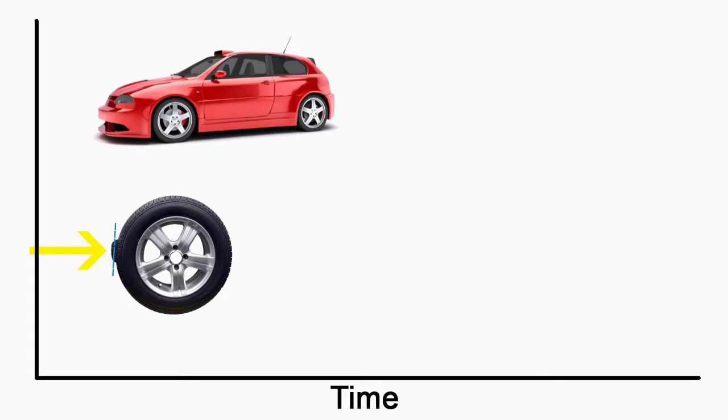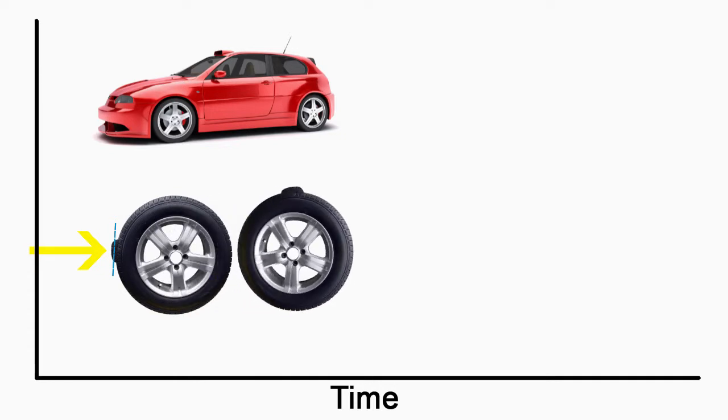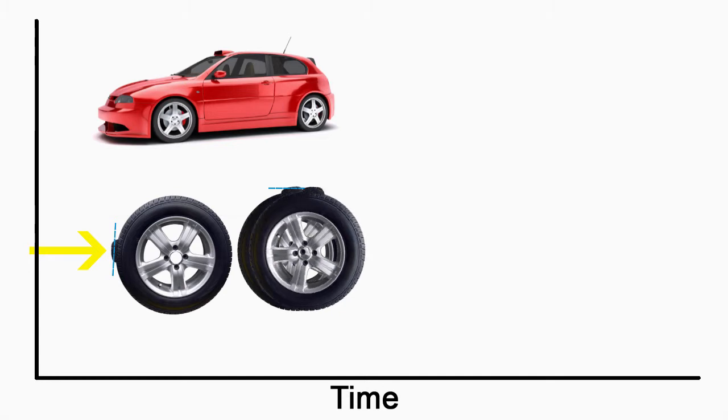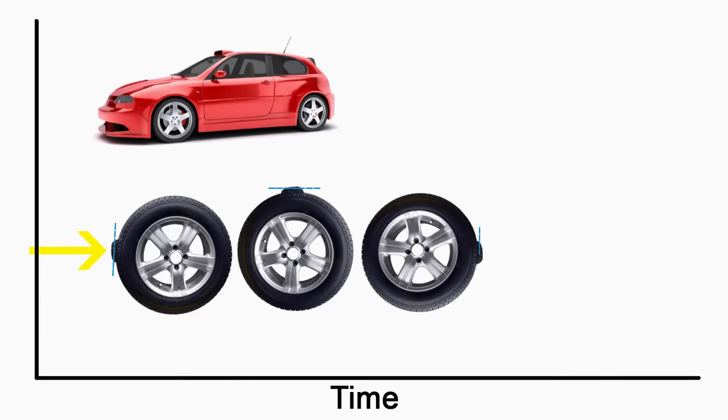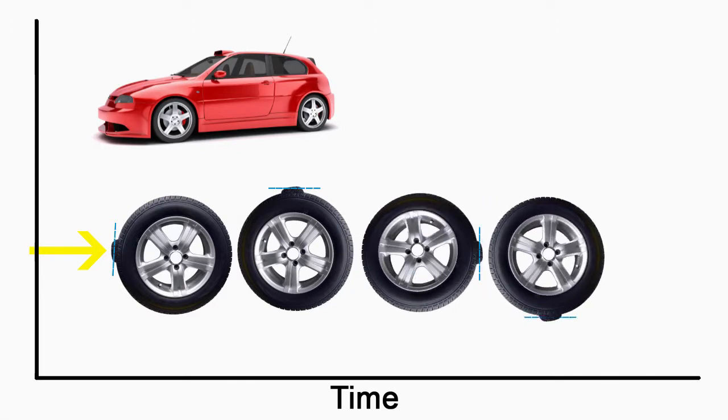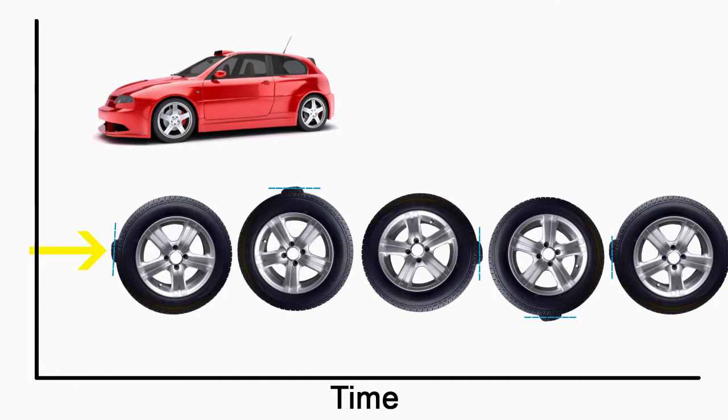As the tire rotates, the new positions will happen later in time. When the tire rotates 90 degrees, the unbalanced weight will be in the 12 o'clock position. Again, we draw a dotted line down to a point that represents this location. It will be further up and to the right because it is later in time. As the tire rotates, so the unbalanced mass is back at the starting point, the 90-degree markings are marked on the graph.